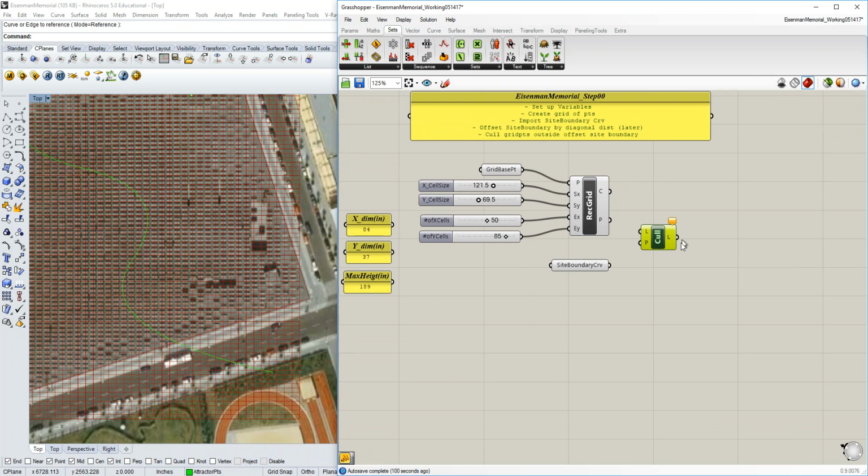Okay, so the cull pattern requires a couple different things. It requires a list and a pattern to cull or to remove. The pattern currently, if you hover over the P, is false, false, true, true. What it's going to say is no, no, yes, yes. So keep, keep, delete, delete. Okay. If you have more than 4 items, it's going to repeat that pattern. So it'll go false, false, true, true, repeat false, false, true, true, false, false, true, true.